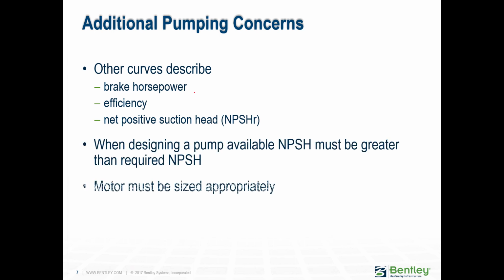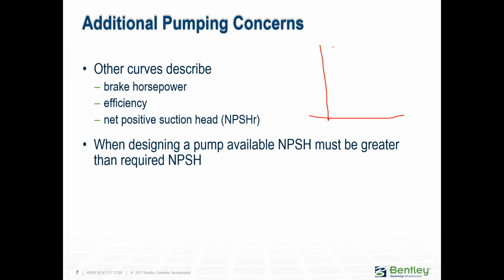What are they for? Typically you have the same graph that we had before, where we had the flow here, and the head, and we have our pump curve. But we also have another curve that's very important, which is the efficiency. We'll focus on those for now, because the efficiency, again, tends to be highest at the design point.